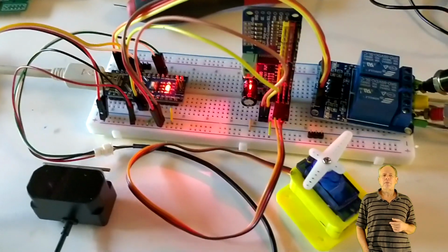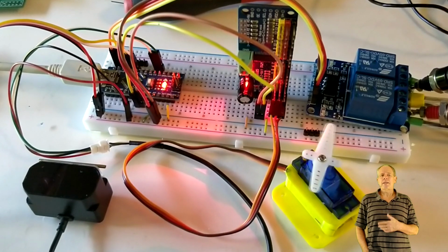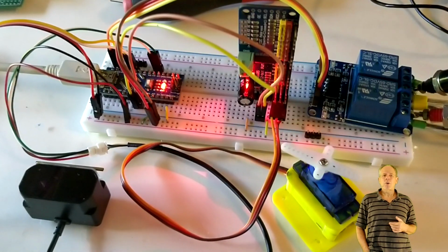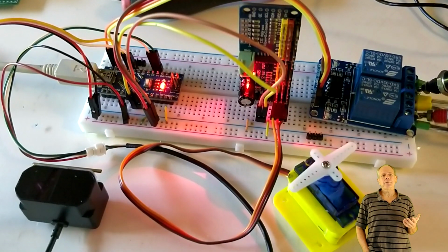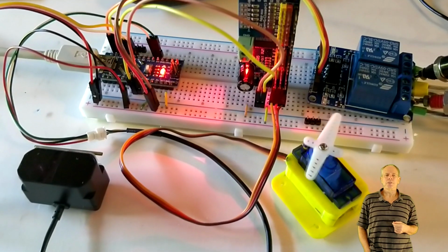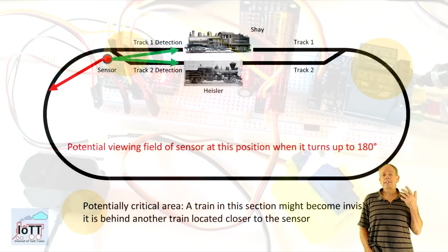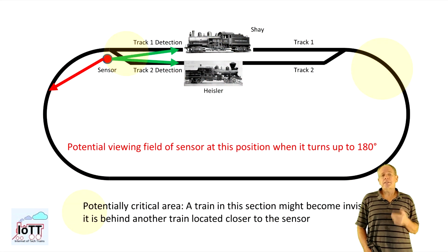The servo example that comes with the library drives servos 1 through 8 sequentially, so we can upload it to verify that the I2C connection to the module is working as it should. And with that, we have all modules connected and tested and can write the sketch that integrates everything.